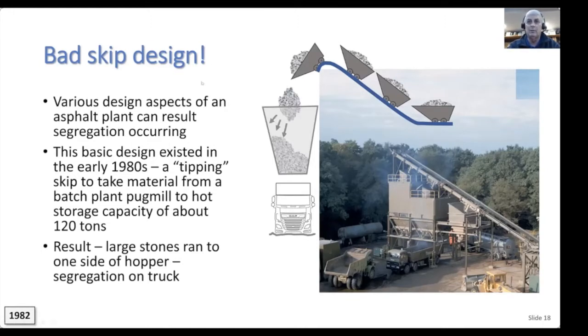And the way it was falling into this hopper, you would get stones running down, and every now and then, not consistently, but every now and then on a truck, you would get a big stony patch of material, and this would result in those patches on the project, and resulted in those ravelling issues. So they fitted some baffles and modified the design a little bit to correct that problem.